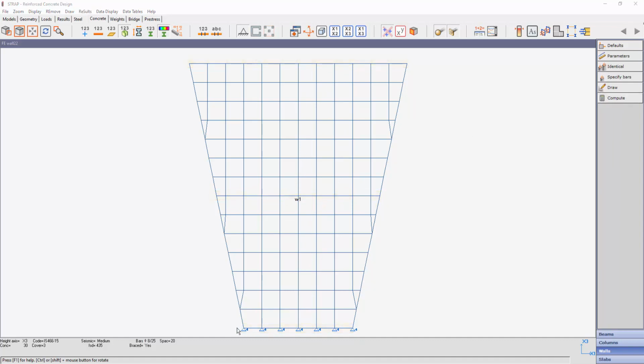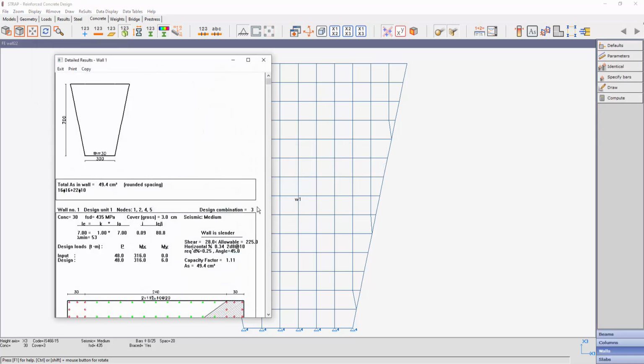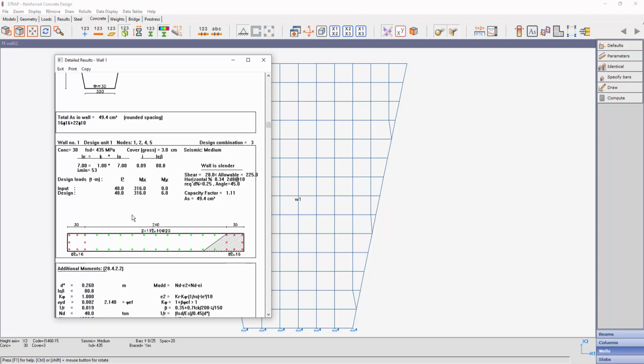The considered wall section for calculation is the smallest section. In our case, it's the section at the wall's base. So in this case, the program will consider the baseline section with the worst wall results between the baseline, the wall's middle, or the wall's top level. In this particular case, the worst results and the smallest section both are at the wall's baseline. But in other cases, this might not be true. So to get a more economic design, the user will need to split the wall along its height axis.